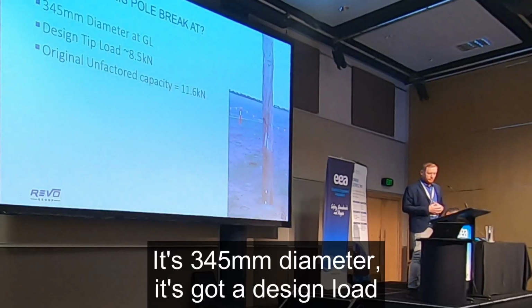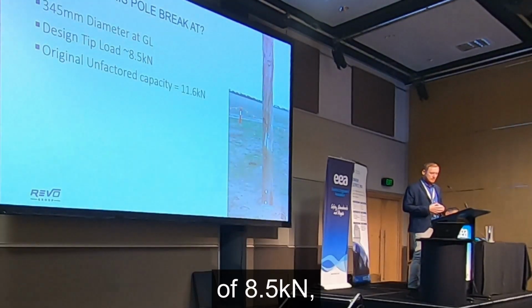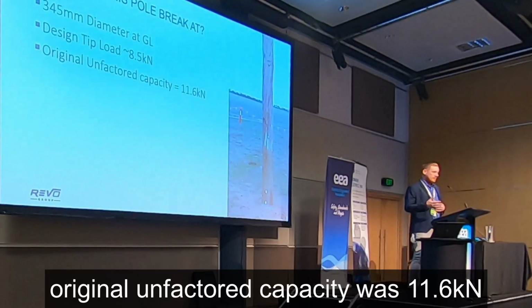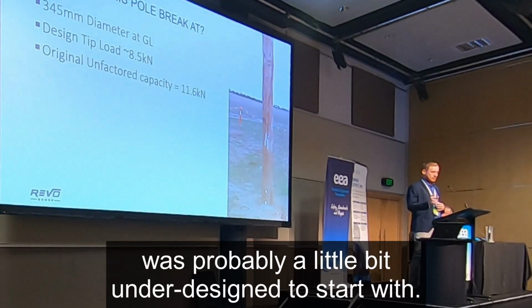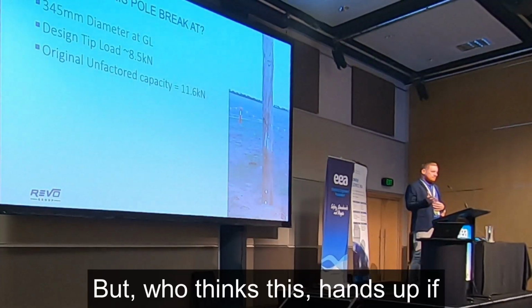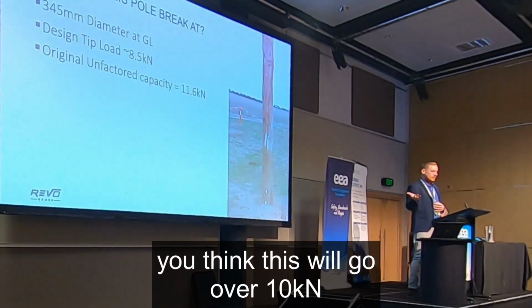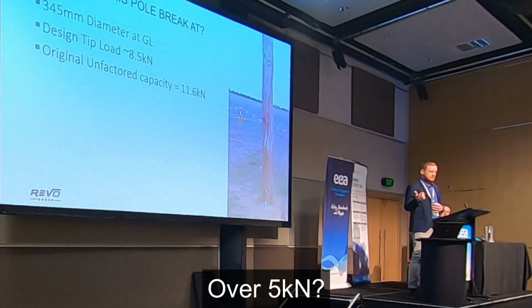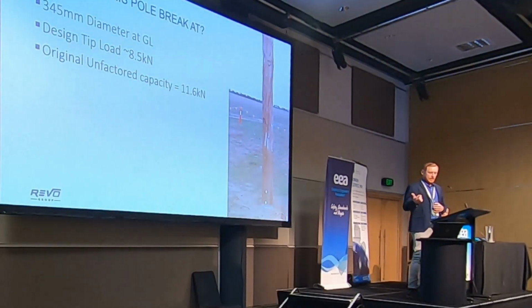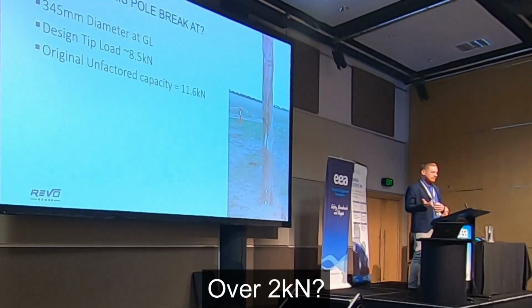It's 345 mil diameter. It's got a design load of 8.5 kilonewtons. Original unfactored capacity was 11.6, which, by the way, probably shows that this pole was a little bit under-designed to start with. But who thinks this? Hands up if you think this will go over 10 kilonewtons. Over 5 kilonewtons? Over 2 kilonewtons? Less than 2.